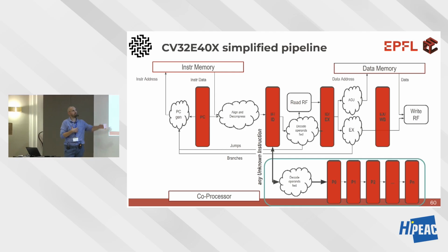If I'm out of order, and this guy is also out of order, then you can reply whenever you like, and I continue doing stuff. If this guy is in order, then I wait for you to finish your instructions, and then I commit. That's implementation dependent, not protocol dependent. So that depends. In this case, the CPU is in order, but on the X interface it can speculate a bit. It's a mix. It's in order, but it's tricking a bit, and it's waiting for you to finish without stalling the pipeline.